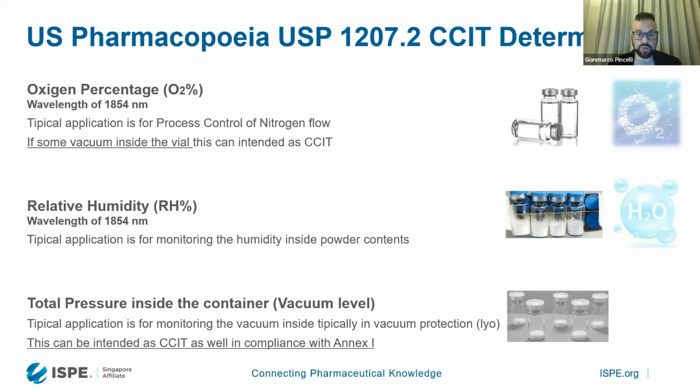If you have one hole and you need a certain quarantine, and this is really important, because the longer the quarantine in between when you cap the product and you inspect the product, the smaller will be the hole, the leakage, that the system can detect. So you can imagine you cap the product on the lyophilization system, okay? You cap the product, you wait 5 minutes, and you make the measurement. You are expecting to have few millibars.